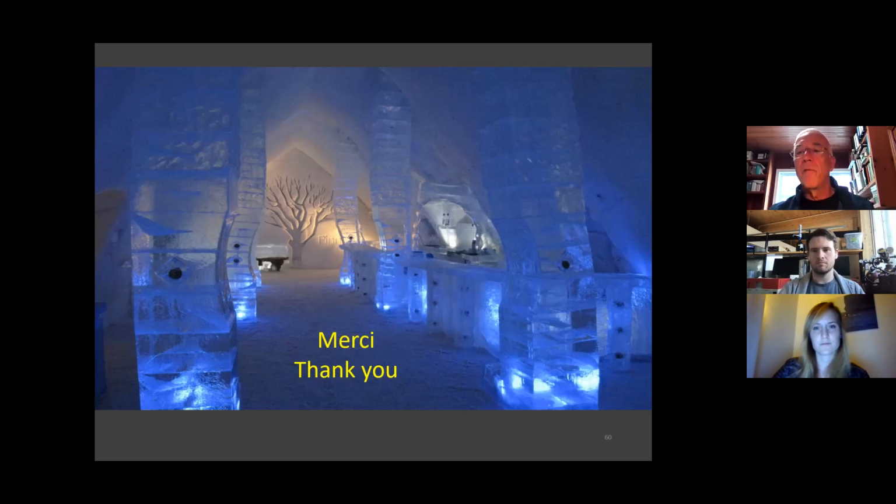Again, I'm not aware of a design procedure to cope with that, but it's possible to assess the creep characteristic of a soil using lab testing. That's very sophisticated testing. There's not many labs in Canada that can do that, but you can get the creep characteristic of the soil and then project the amount of settlement that's going to occur over time. And again, this is a question of tolerance at that point.